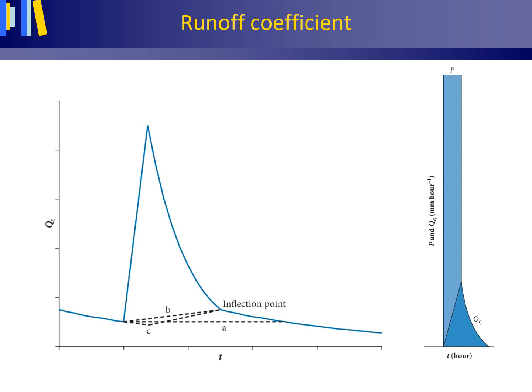Usually in plots of storm hydrographs, discharge and precipitation are presented using different units. For instance, cubic meter per second for discharge versus millimeter per hour for precipitation, and thus along differently scaled axes. The first impression of such figures may be that a large percentage of precipitation is discharged as quick flow during storms, which may be misleading.